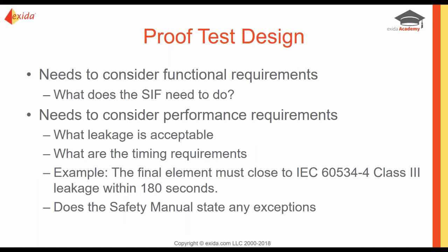That has a lot of great information that you need to consider when you are designing your proof test. If leakage is important for you, if you're a tight shutoff application, then you need to consider testing for leaking when you're doing your proof test. What if leakage is not important for you? Then don't worry about it, but your timing might be very important. You might have to close a valve within a certain amount of time, and you might want to time a valve. So it depends on what is most important in your SIF design to what you need to design your proof tests around.